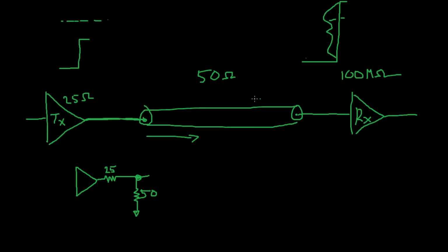When that signal makes it all the way back, then we'll see the other half of that waveform show up, and we will see something along these lines where it will bounce back and forth, and eventually it'll settle out. Now, this is an incredibly ugly reflection that I've shown here, but I wanted to show it as very exaggerated to give you the understanding of what's going to happen if you have mismatches here.